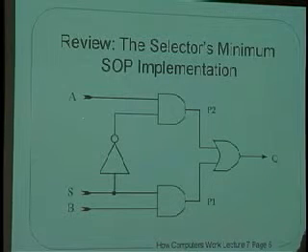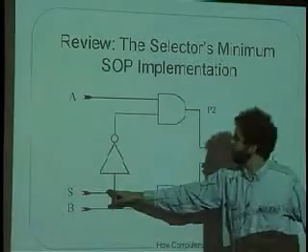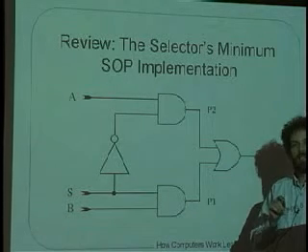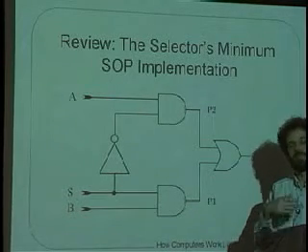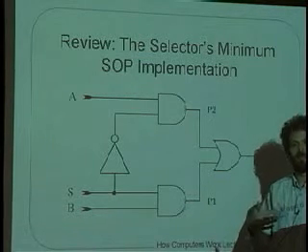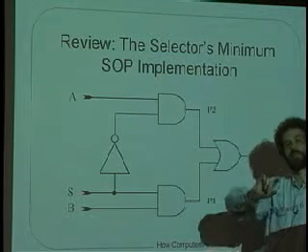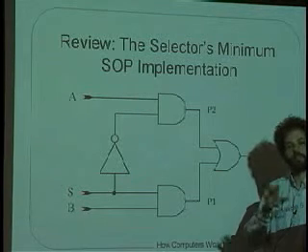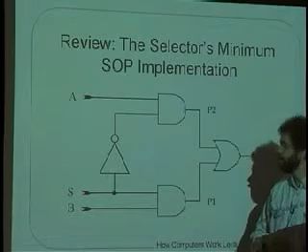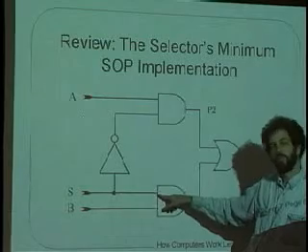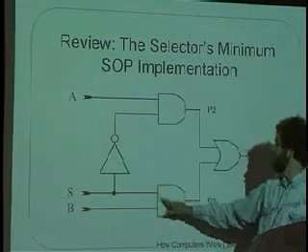Can you just say again where you can tell if S is high or low? Sure. The logic convention I'm going to use by default, unless we say otherwise, is that a high value or a high voltage is equivalent to a 1, and a low voltage is equivalent to a 0. Now, later on in the course, we're going to talk about sometimes when you want to flip that. But by default, just assume that we're going to use what's called positive logic, which is high equals 1, low equals 0. If S is a 1, then the AND of 1 and 1 is 1.